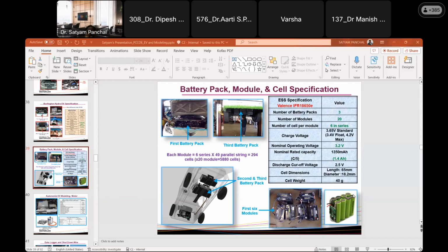You are talking about lead acid battery. They are recycling lead acid battery, and they developed their own machine, but that is with water. Lead acid battery is typically only a 12-volt system. Typically we use it for start and stop of the vehicle, radio, wiper, and electrical accessories, for smaller applications. But for vehicle driving, we cannot use lead acid battery. We have to have lithium ion battery, which has higher energy density and specific energy.